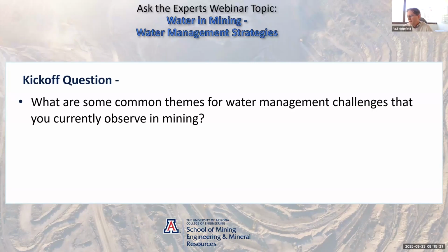Yeah, I just had one more thing. When you get the water out from pumping wells or drains or whatever, you either use it for dust suppression or whatever in the pit, or you remove it entirely from the pit and you don't leave it to re-infiltrate in unlined ponds or discharging to the benches, because that's just going to re-infiltrate and maybe cause increases in pore pressures as you move forward. So when you get the water out, you need to remove it from the pit or use it.